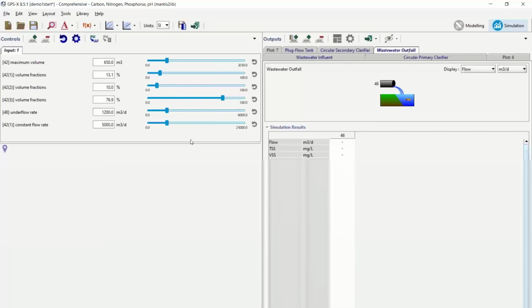Okay, so here's our profiles again. Oh, no, that's not the profiles. This is the profiles. And here we go. All right. So now what we can do is, I noticed that, of course, we got lots of performance in terms of nitrification here, but a relatively small amount of this tankage is available for the fermentation step, for example.